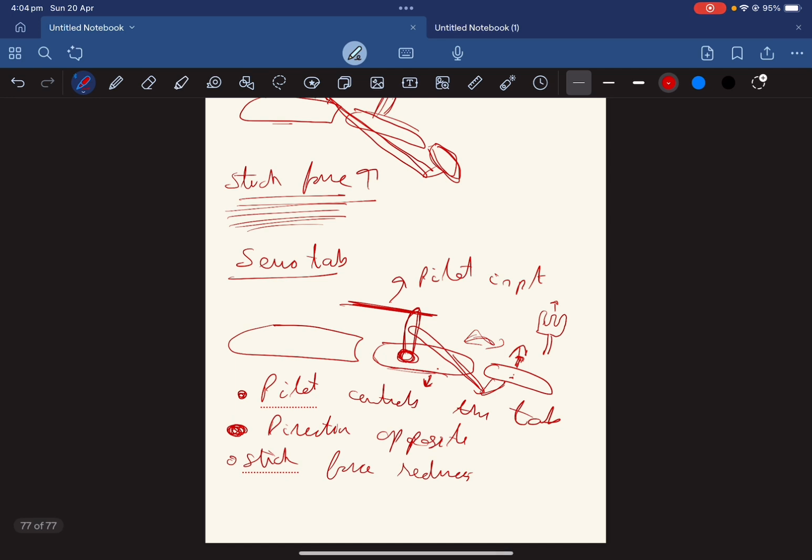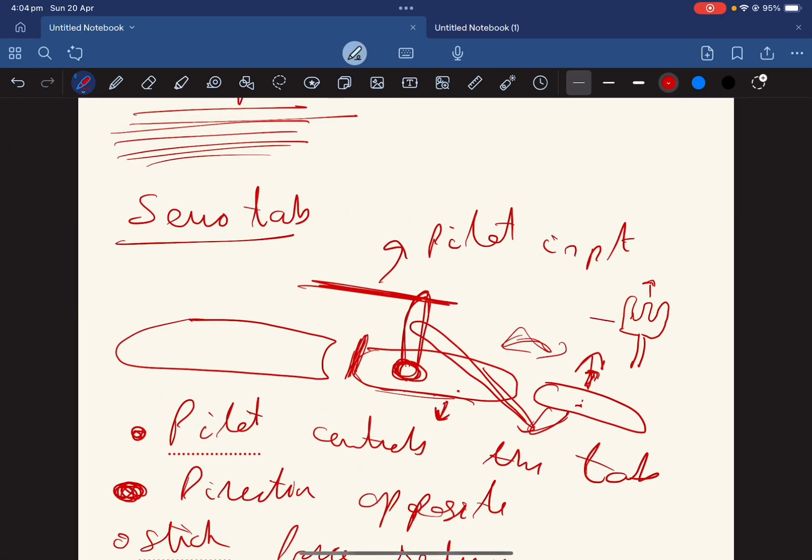What happens if you have external control locks fitted to the control surface? Say you have locked the control surface, so when you park the aircraft, it doesn't move because of the wind. The thing is, your cockpit control would still be able to move left, right, up and down. This is because you're controlling the tab, not the control surface.